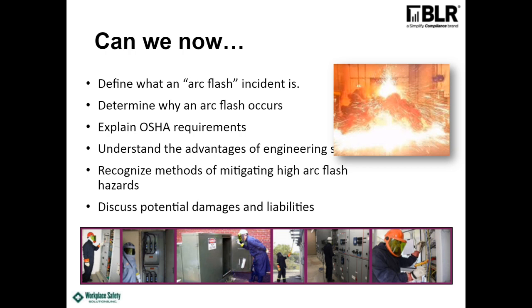And then we talked about the advantages of engineering studies. It gives you a lot more detail and provides a label, tells you what it is, and it gives you information. The problem with the tables, they can give you information, but people don't tend to do an assessment to determine what their fault current and clearing time is so that they know they can use those tables. And that doesn't seem to happen out there, so that's an issue.